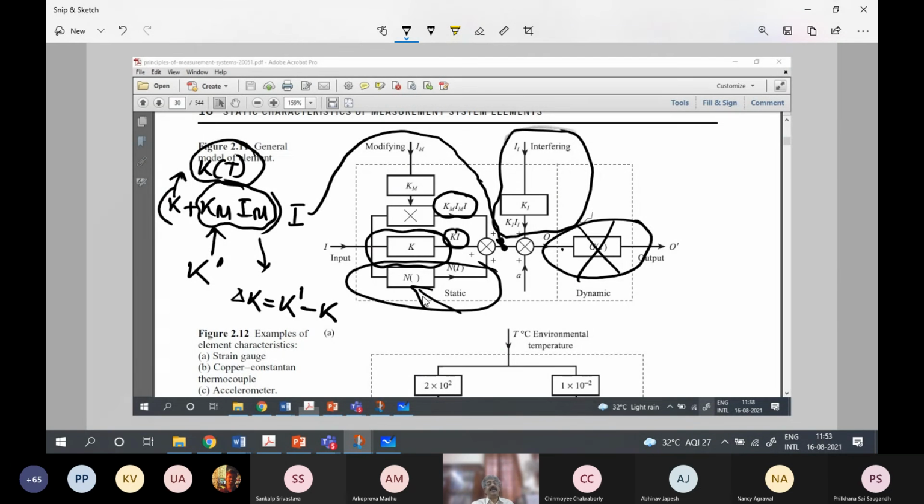So actually there is a nonlinearity. You may like to call it a desired part of the instrument. You may like to call it an error. Whatever you like to call it, there is a nonlinearity of the physical process of measurement involved, which generates the result. You could absorb it within error specification. If you are using a simple thermocouple application over a narrow range, you can say that this thermocouple is linear. Directly from the voltage, you can get the temperature.